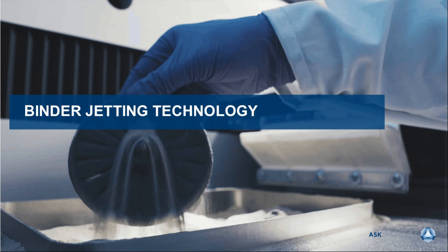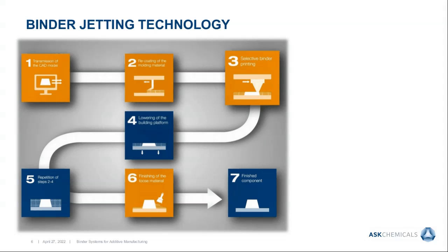Let's take a look at binder technology itself. Many of you may already know the process of binder jetting, or additive manufacturing, coming from a 3D model on the computer, which is then sliced into two-dimensional images. A thin layer of molding material, typically around 300 microns thick, is spread out on a building platform and afterwards selectively printed with binder according to the 2D data generated.